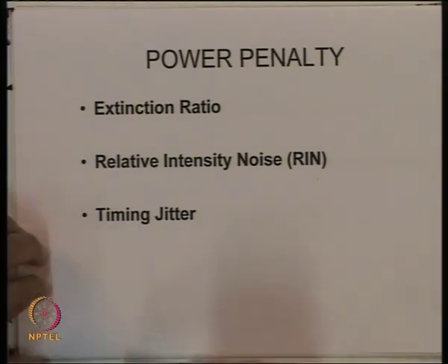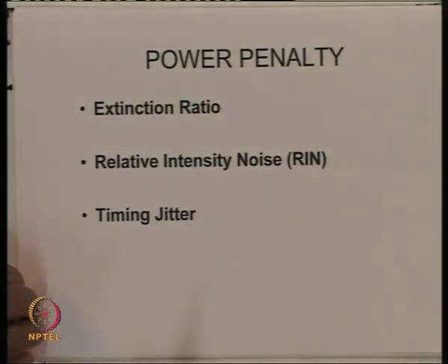So, in this lecture essentially we investigate each of these power penalties. Of course, when we are investigating one power penalty, we assume that the other degradations are not there. So, at a time essentially we account for the power penalty due to one effect, and then we say the total power penalty will be the sum of all the power penalties in terms of dBs. So, let us first look at the first power penalty, which is the power penalty due to the extinction ratio.